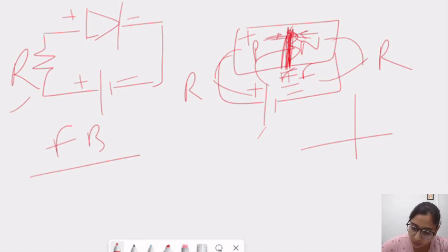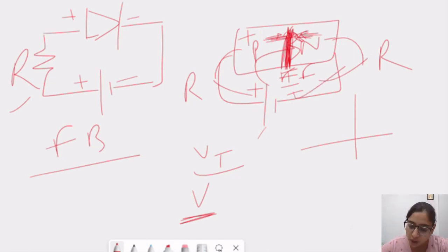Now here, two things we have to consider: one is the thermal voltage, and one is the applied voltage. Due to the applied voltage, we already saw that the depletion region becomes thinner, and the electrons and holes try to move towards the layer, take part in conduction, and start flowing the current IF. But due to the presence of temperature inside this depletion layer, a few electrons or holes recombine.